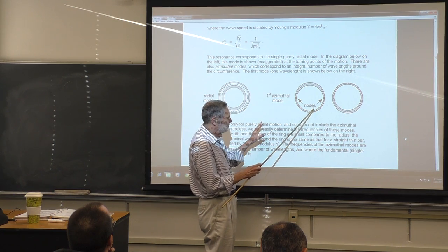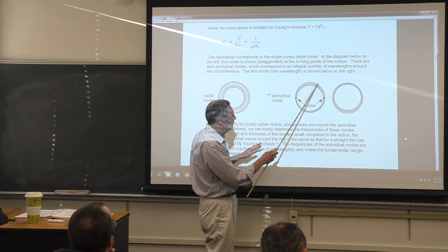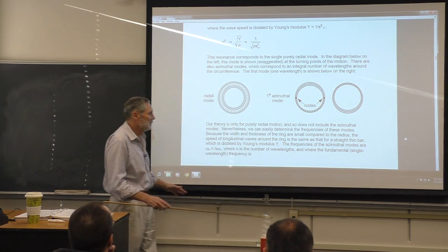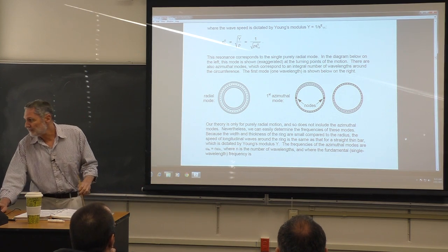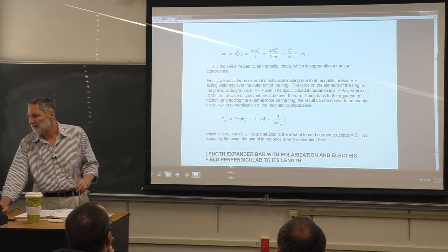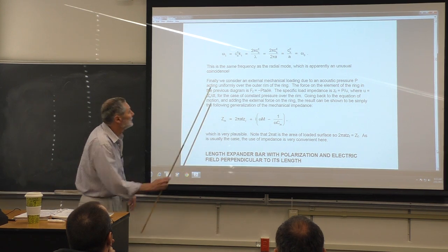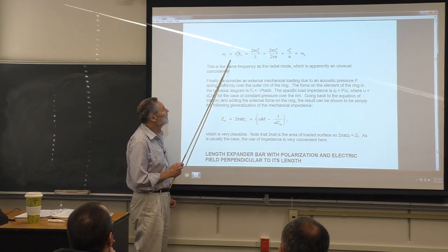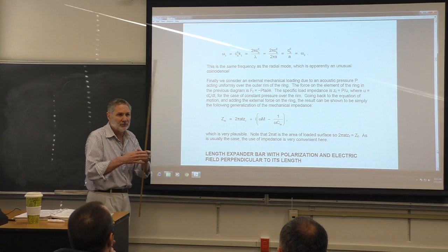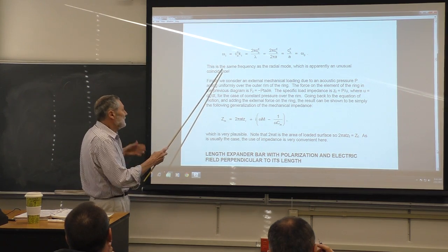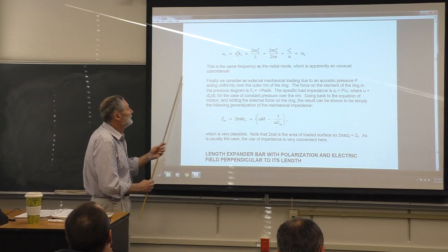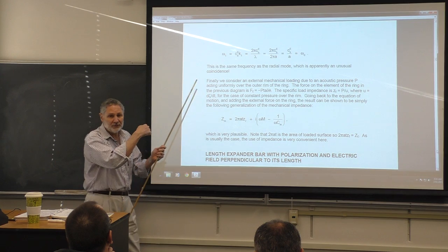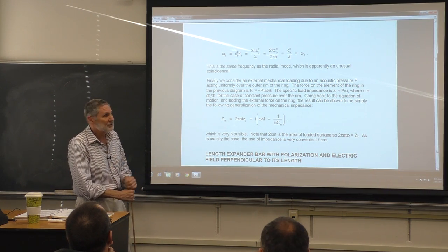Let's just think of wavelengths here that are going to tend to be long, roughly large compared to the transverse dimension. So it's going to be Young's modulus. So what's the frequency? Well, now watch this carefully. Look for sleight of hand here. This is really amazing. We're going to use a 1 subscript for that mode. We use 0 for the radial mode. And the next one will be twice this frequency. They'll be harmonic. So omega is equal to ck, right? Where c is, of course, on the previous slide, the speed of sound due to Young's modulus.